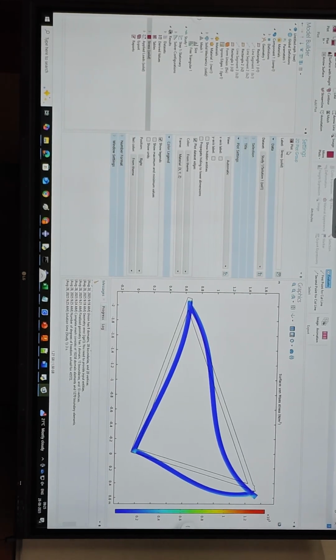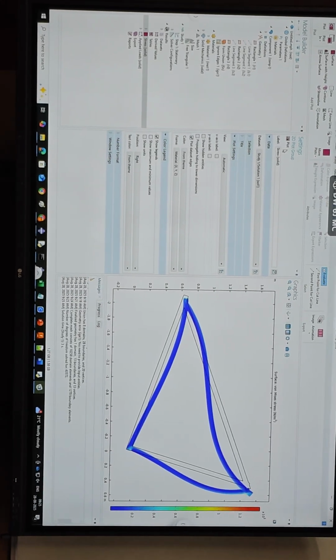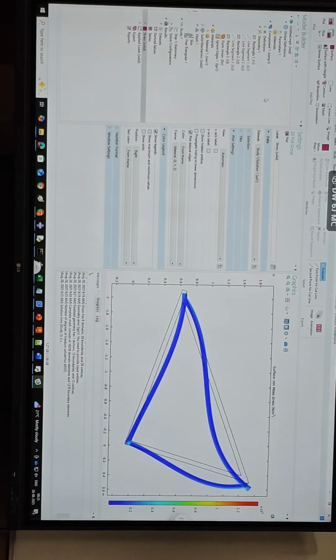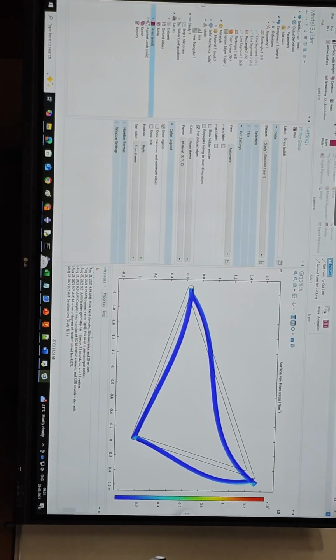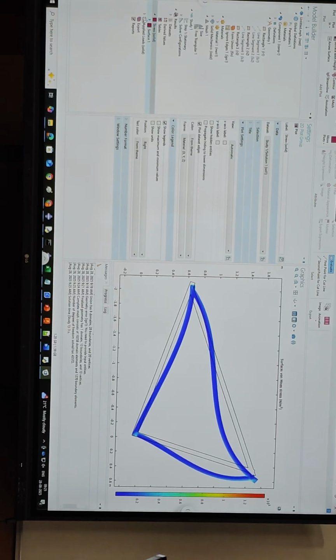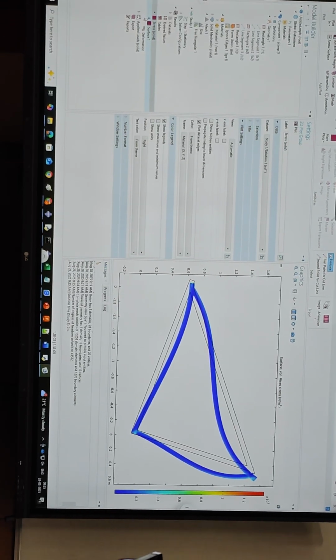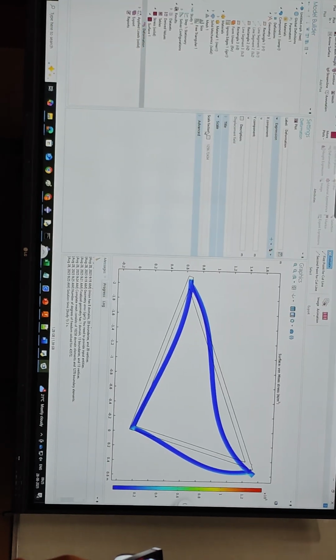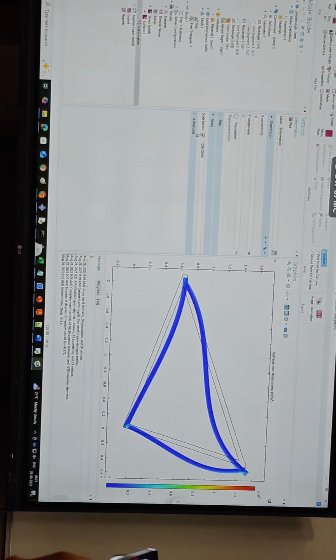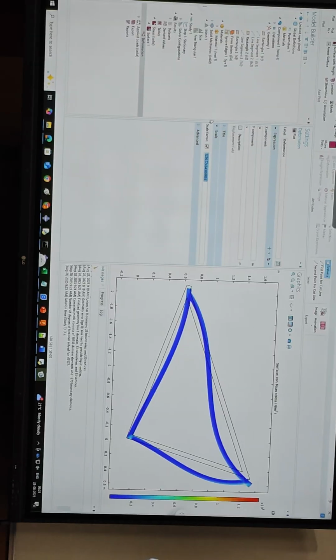So now what you get is similar to MATLAB. You'll have some cubic interpolation of the deformation. Then you can come here to stress. You see results. You see stress here. Drop down on stress. You have surface. It's a surface plot. Drop down on surface. You have the deformation scaling. So you notice it's been scaled by like 1,256. So you can just reduce this if you want.